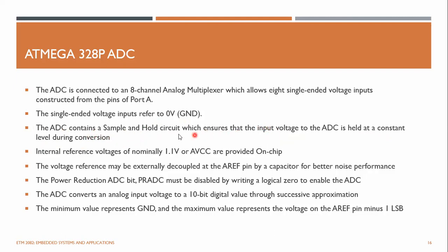During that period, the capacitor in the sample and hold circuit should hold the voltage, otherwise the values will not be accurate. It has an internal 1.1 volt reference. Sometimes you can use the AVCC pin or an external supply as your reference. When you are using AVCC, you have to couple a capacitor to the AREF pin in order to eliminate any noise.